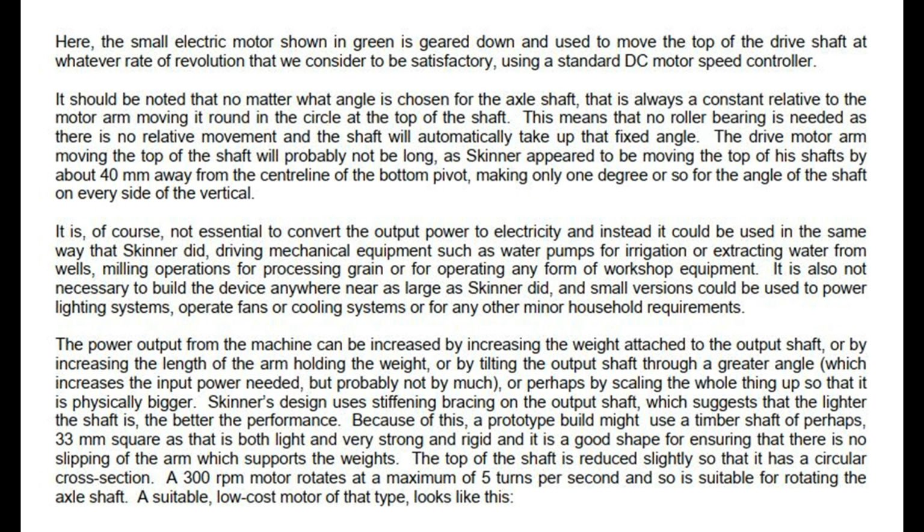The power output from the machine can be increased by increasing the weight attached to the output shaft, or by increasing the length of the arm holding the weight, or by tilting the output shaft through a greater angle, which increases the input power needed, but probably not by much, or perhaps by scaling the whole thing up so that it is physically bigger. Skinner's design uses stiffening bracing on the output shaft, which suggests that the lighter the shaft is, the better the performance.